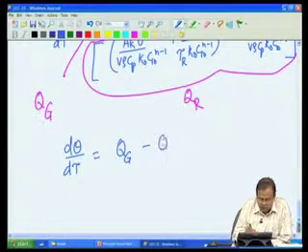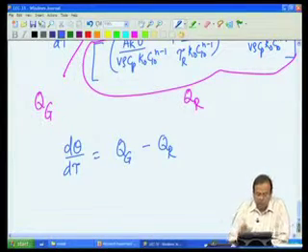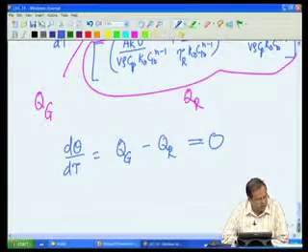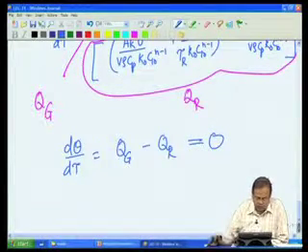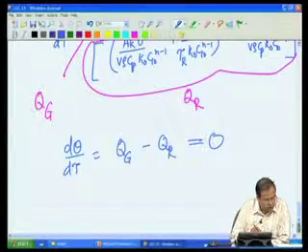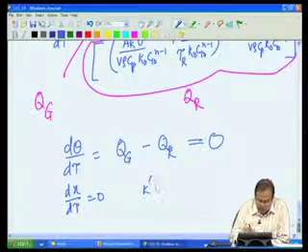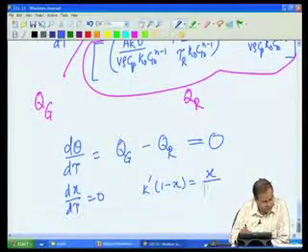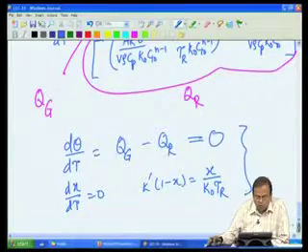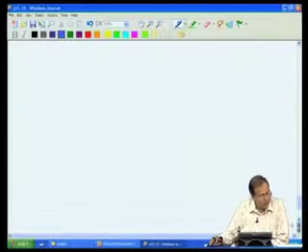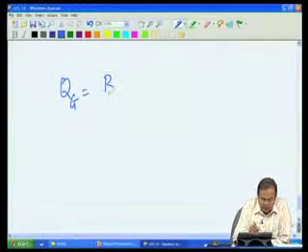But the point is, once again we can write this as Qg minus Qr, and as you know, in a stirred tank reactor, we have a steady state. So, this is actually a precise description. Okay. This is our precise description, in addition to, of course, our mass balance dx d tau also being equal to 0, which if we consider a first order reaction will give us this particular relationship. So, now if we combine these two mass and energy balances, we can actually represent our energy balance or Qg term by combining mass and energy balances.